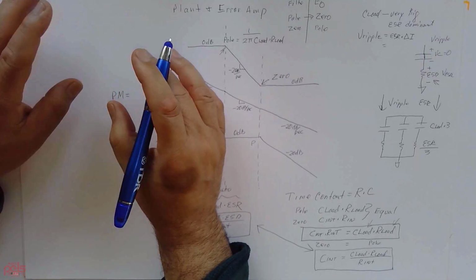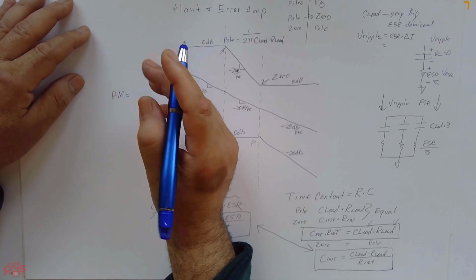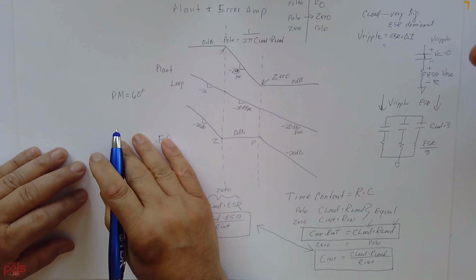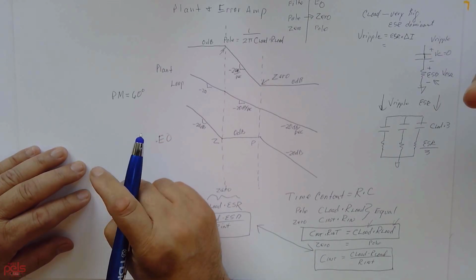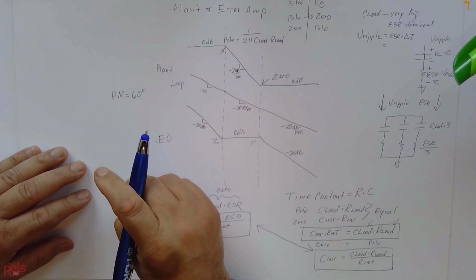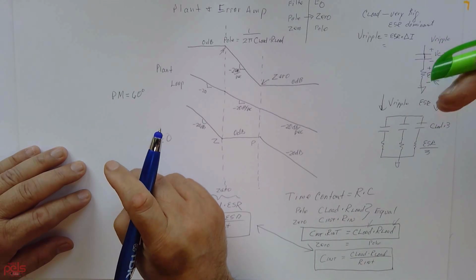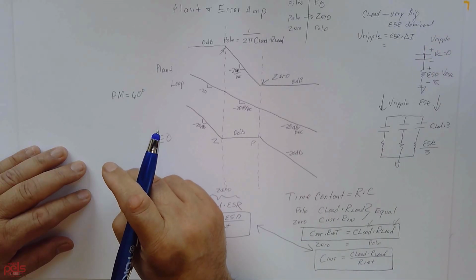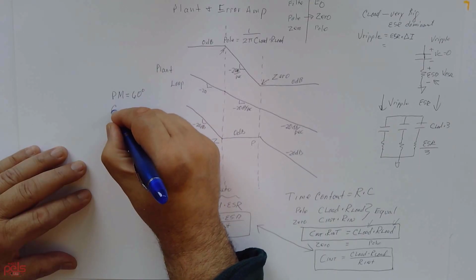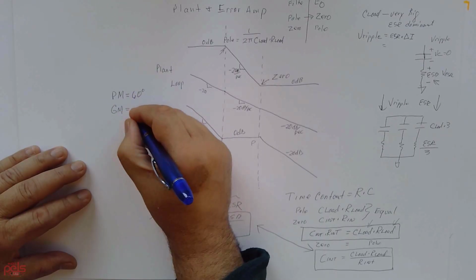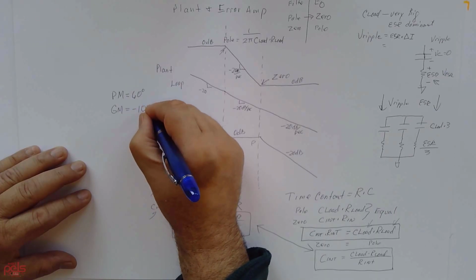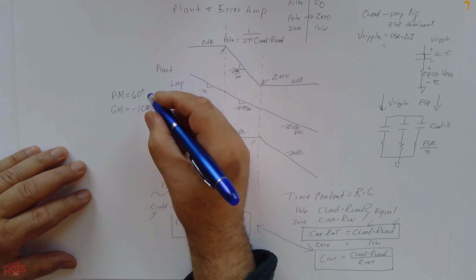And usually, as far as the figure of merit, phase margin, what do you use at your company? Is it like 60? Yeah, 60 degrees. At least for space applications, there's going to be aging and temperature, so the higher we get without getting sluggish, the better off we will be. And for gain margin, it's about negative 10 dB.